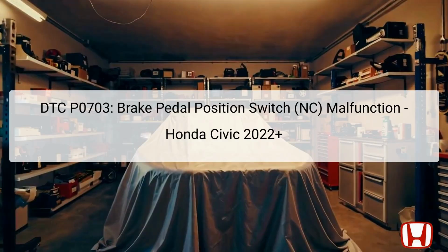The diagnostic trouble code DTC P0703 indicates a malfunction of the brake pedal position switch in the Honda Civic models from 2022 onwards. This component is responsible for sending a signal to the powertrain control module, PCM, informing it of the brake pedal's position. It is vital for ensuring that the vehicle's braking system functions as intended, thereby impacting cruise control and idle stop features.